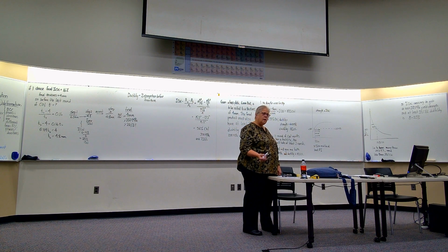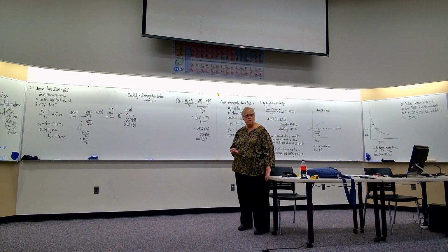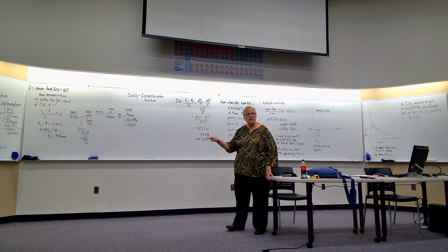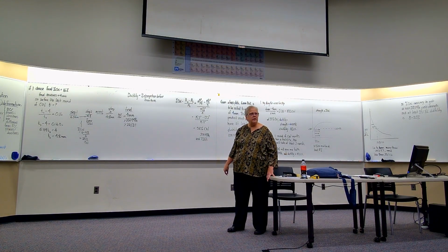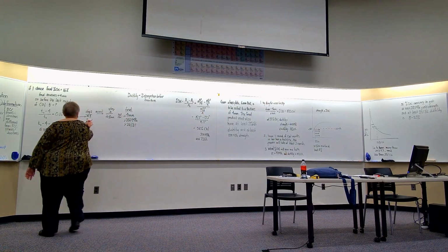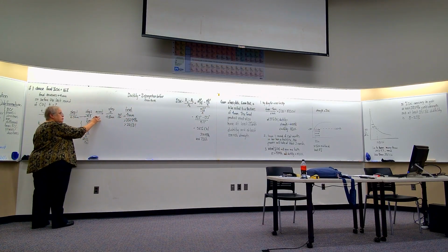If you take 20% cold work, do you sum them up on each step? No, because you anneal between each step, so you get rid of it. So I had 20% cold work here, then I anneal, now I have no cold work.